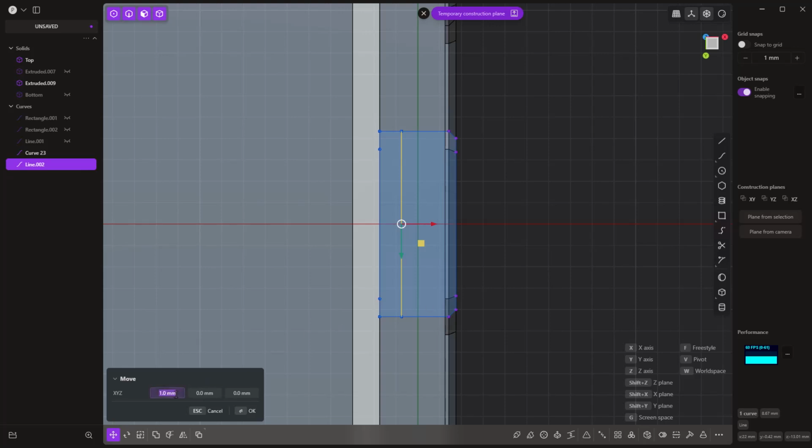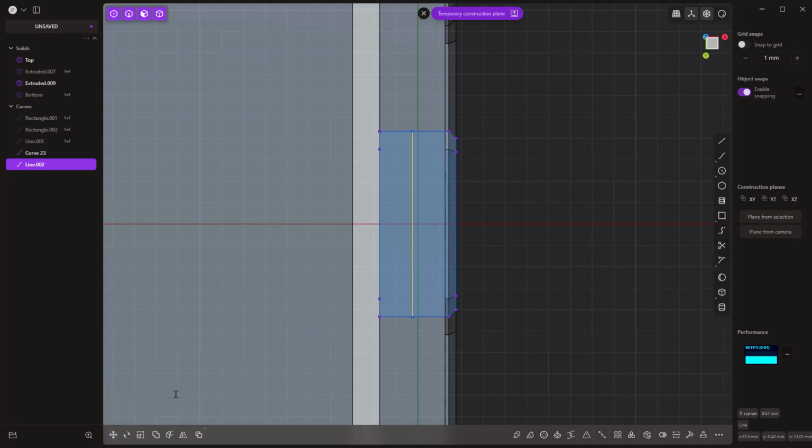So I'm actually going to make it 1.5 millimeters, which will be half the wall thickness. That's how big the piece is that's going to connect the push button to the rest of the body. But we also need to remove material. We're going to have to leave a fairly thin wall here to allow that to flex.